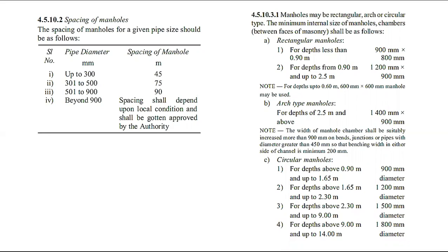Sometimes, based on the requirement and site condition, it may be 28 meter between the manholes or 37 meter. It will come based on the site condition only. So on average, 30 meter you can maintain for the main manhole, where you will use 160 mm pipe. For inspection chamber to inspection chamber, you are going to use 15 meter only maximum. IC means inspection chamber.